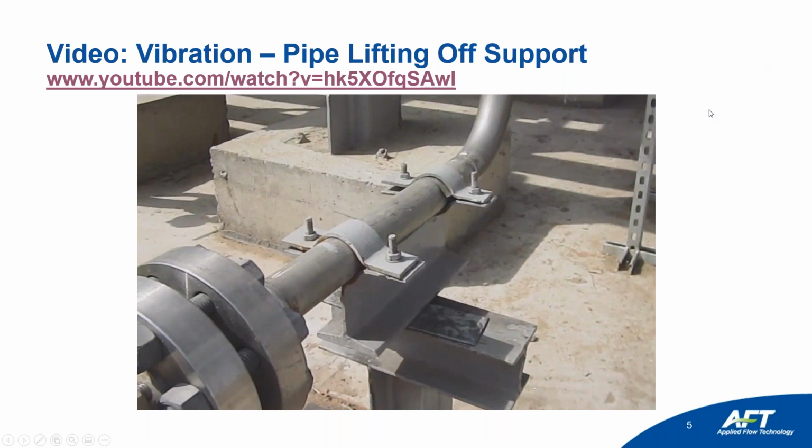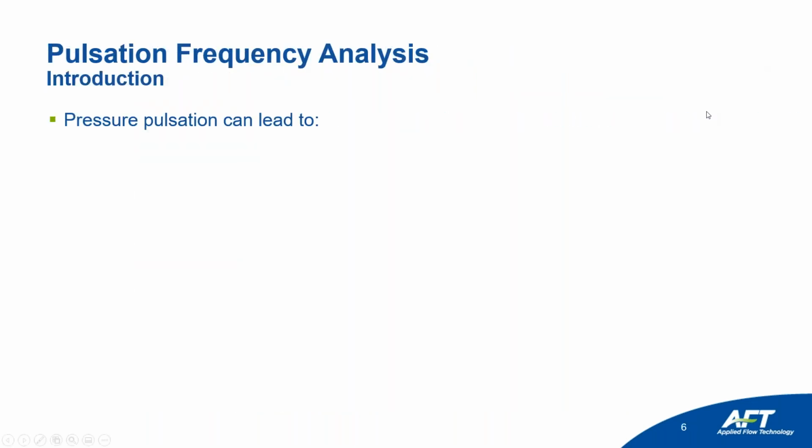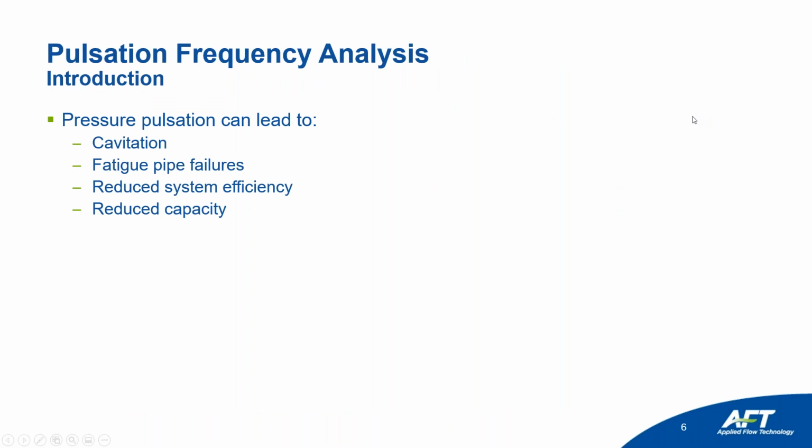So pressure pulsation is something we want to predict, because pressure pulsation can lead to cavitation, fatigue, pipe failures, reduced system efficiency, and reduced capacity.